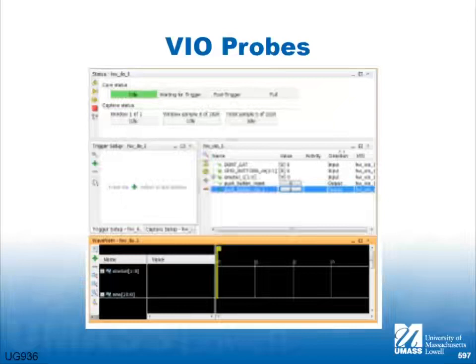If I had a 32-bit multiplier in simulation, it's going to take a certain amount of time, right? Because simulation clock cycles go pretty slow. If I could put it in here and run it at, say, half the speed of the ASIC, I could get a lot more vectors. I could also put pseudo-random number generators in for my stimulus that would give me that.